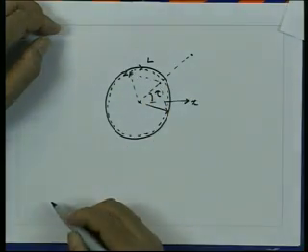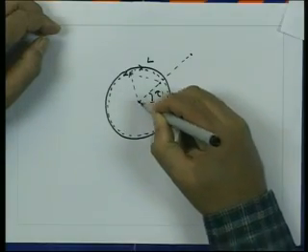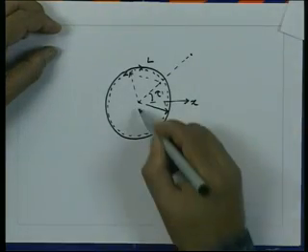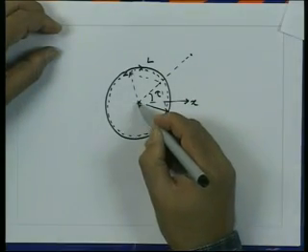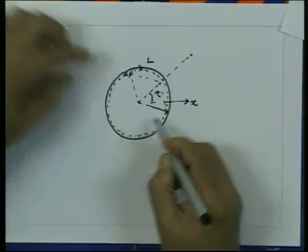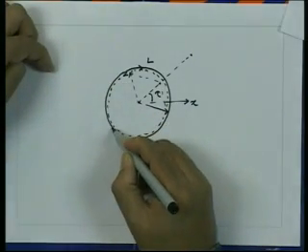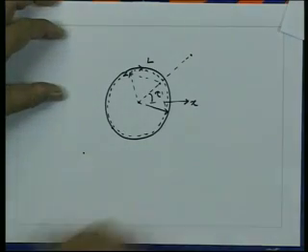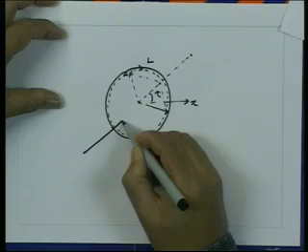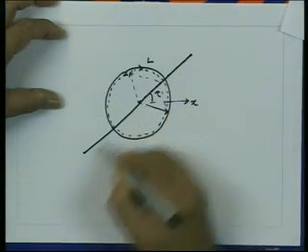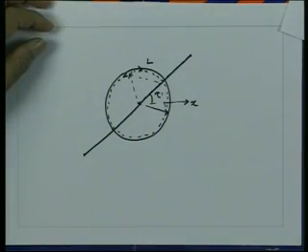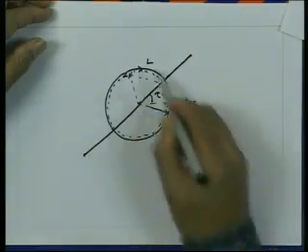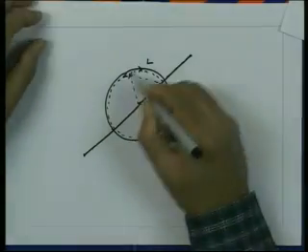So, the value will be this, and when the two vectors become perpendicular to each other, at that time they will cancel and the amplitude will go to 0. And when the vectors rotate further, essentially the point will move like that. After half cycle, the two vectors will come exactly in the opposite direction here, they will again add, and you will get an amplitude which is double. So, you will get a polarization of the wave which essentially will draw like that. So, this amplitude now will be double the amplitude of the individual circularly polarized waves.